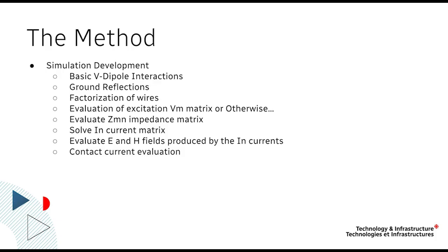After that, it will split the domain again to fit the frequency that you're trying to simulate. Usually one quarter of the wavelength will be the maximum size of the features that we simulate. So higher frequencies will generate smaller segments and more compute.